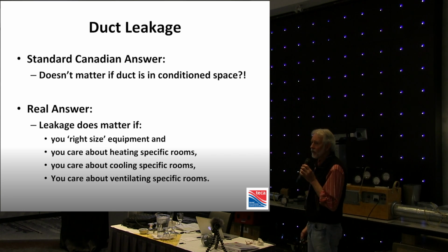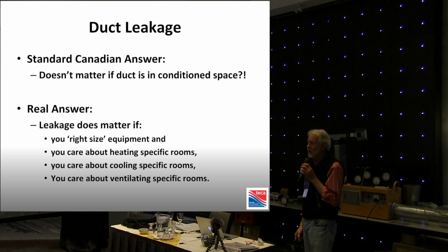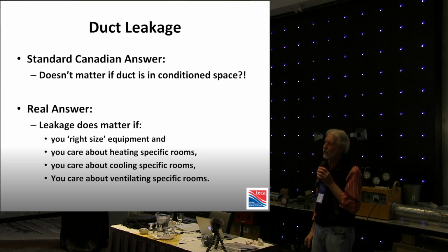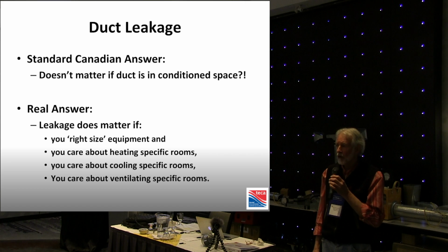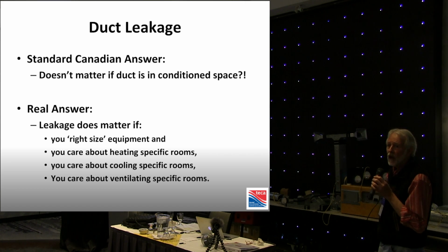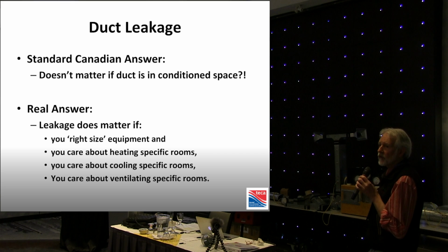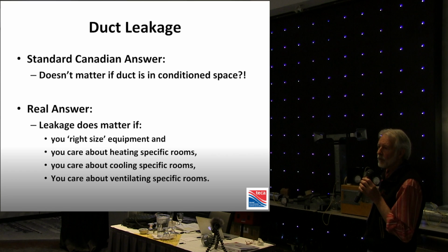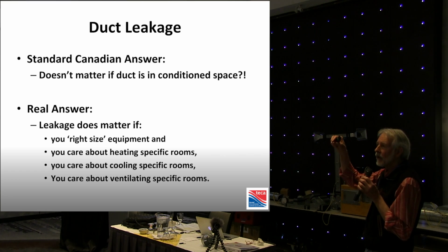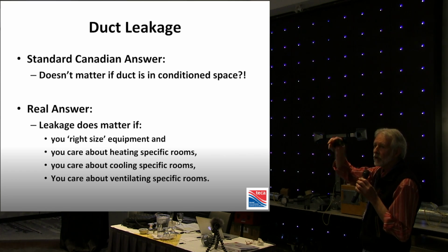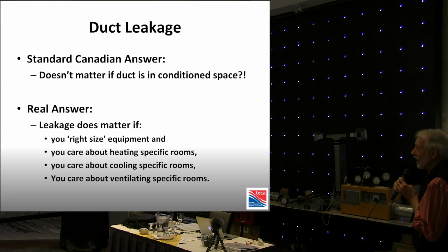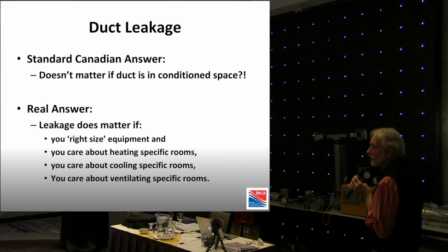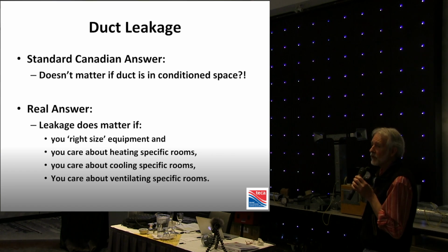The conventional answer in Canada is, we don't care, because our duct, by and large, is in conditioned space. So the age-old thing we get from NRC for the last 50 years, and I should admit, after sitting on Part 6 for about 5 years, 20 years ago, before I gave up and disengaged, NRC has no mechanical capability. They're a building enclosure-centric organization, and the expertise in mechanical does not exist. But the philosophy in Canada is leakage doesn't matter. And it doesn't really matter what we do if the duct is in conditioned space, because the loss from it will be into conditioned space.